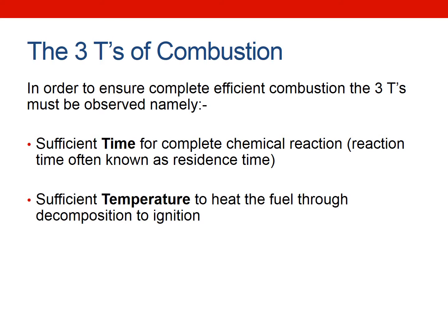You need sufficient temperature to heat the fuel through decomposition to ignition, and also to sustain combustion. In a spark ignition engine, the temperature is obviously initiated by a spark plug, and in a compression ignition engine, as we discussed last time, it's through the heat in the air as the charge is compressed. And it's not just the temperature to initiate combustion, but as I say, to sustain combustion as well.